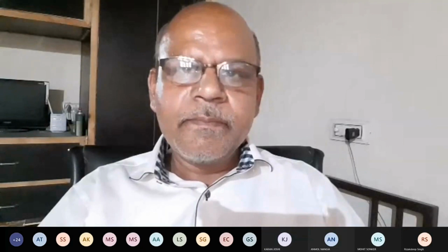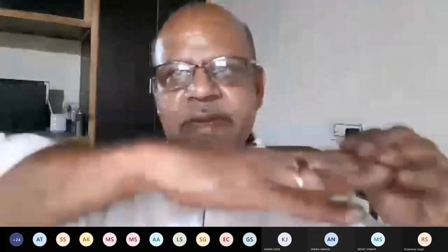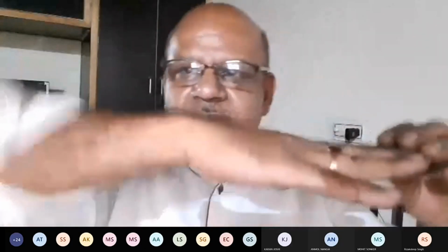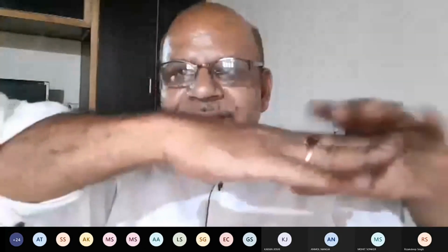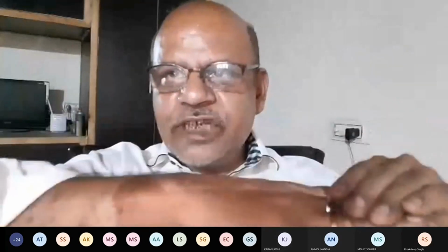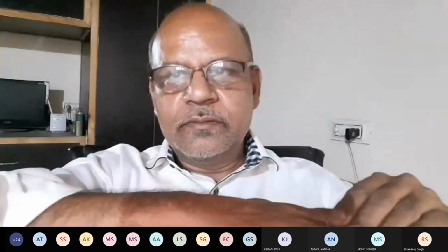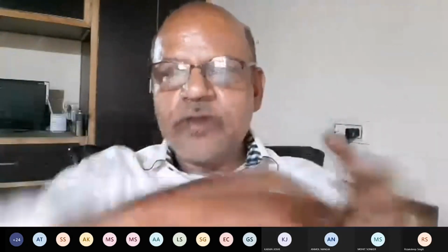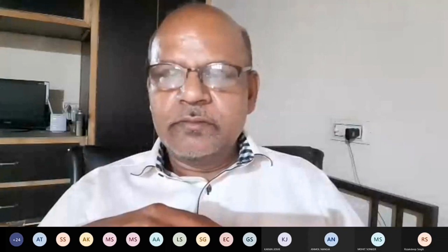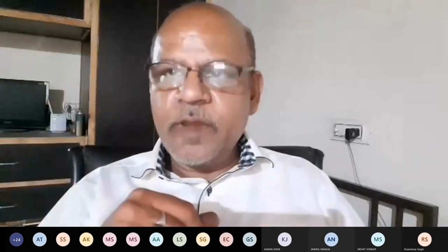Squat. Very good. In the shallow water effect, the ship is moving, she sinks a little bit, and there is a possibility that she is down by head or down by stern. Because of motion, the bodily sinkage of the ship is taking place, so that also goes down. So squat, or the shallow water effect, must also be considered.